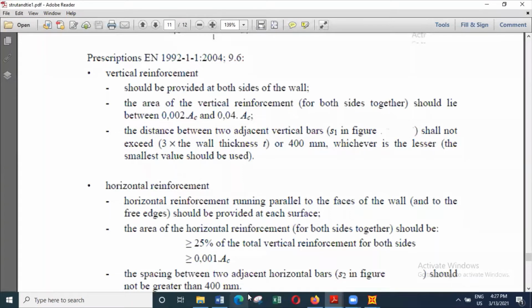So basically, you can see now this is one of the possibilities that you might encounter with pile foundations, where two piles are supporting a wall. In that situation, the upper part of the wall will behave just as a normal wall, whereas at the ground level, the wall will behave in a different way.